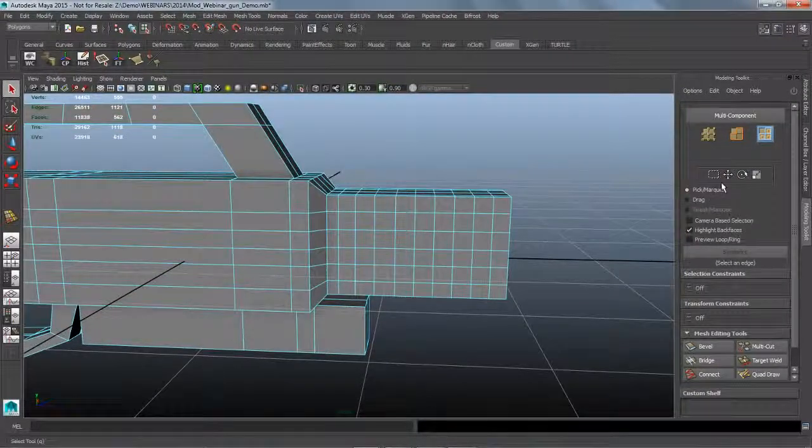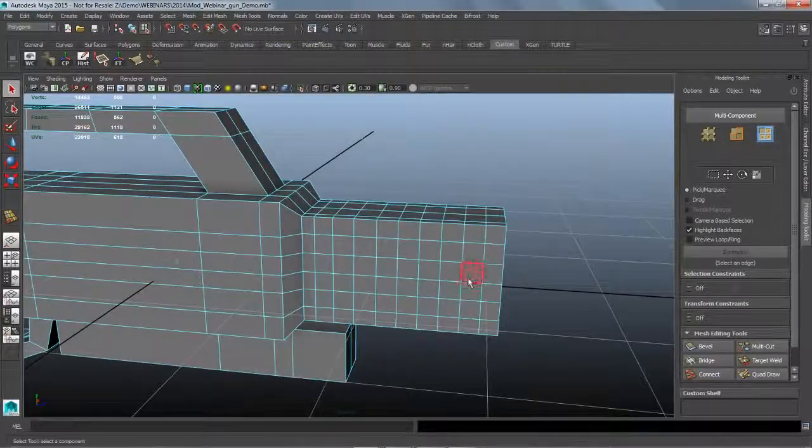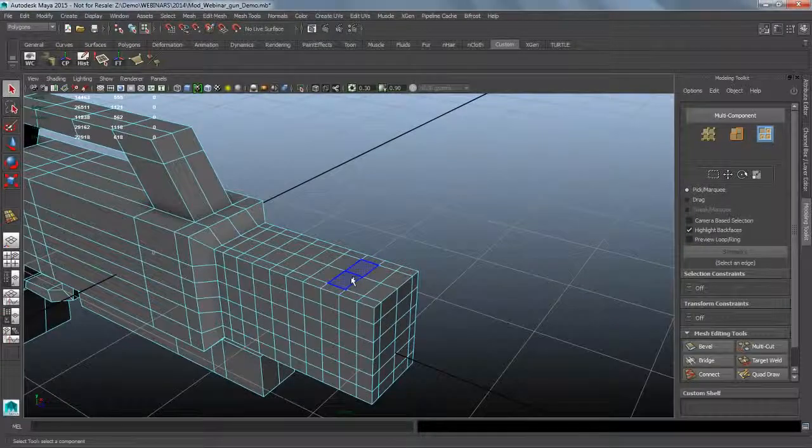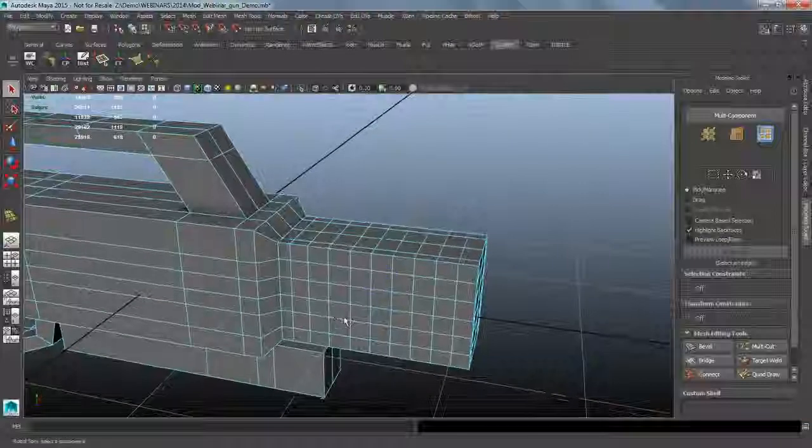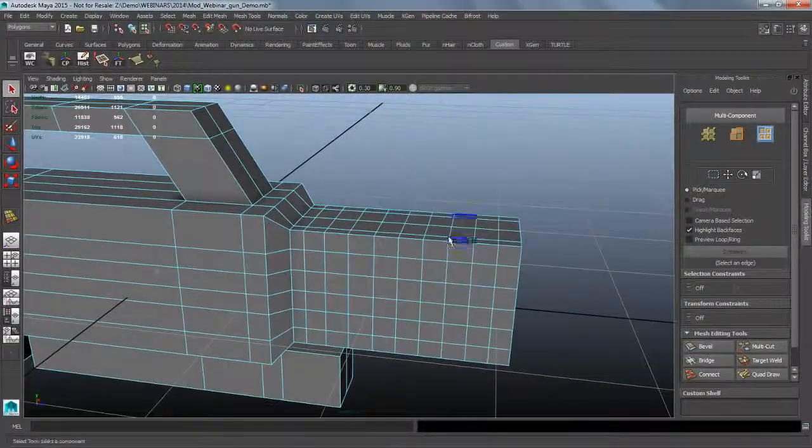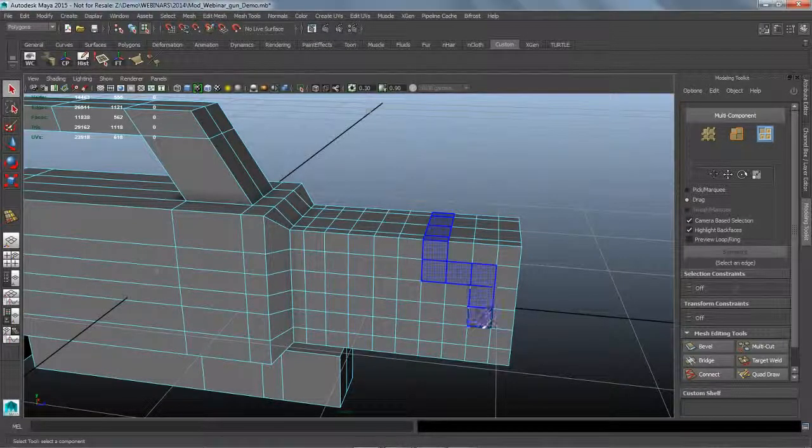And you'll see that we have these different ways of selecting faces. If I hit tab, it switches to drag, and this is actually a really nice way to work. First thing I'm going to do is turn on my symmetry, and you'll see that I'm getting these blue highlights as I go. So I can work with symmetry with any of my tools as I model. If I hold down drag, and turn off caps lock, I'm holding down drag, and you'll see that it's selecting over here. I'm effectively paint selecting as I go.